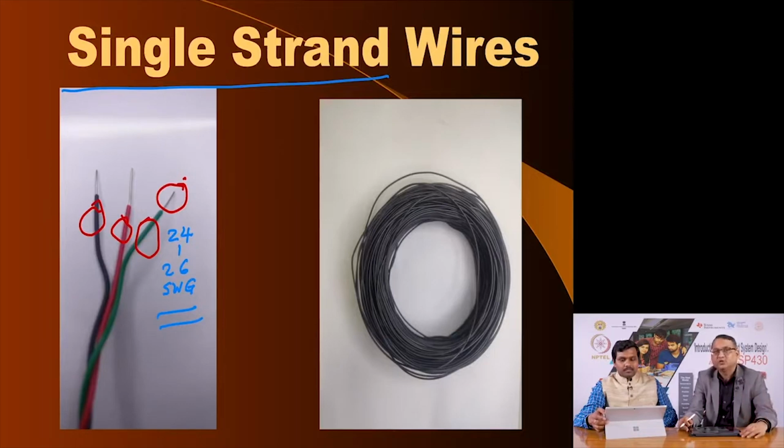On insulation, let me also make a point that the typical insulation that you would get in the market is plastic insulation. However, apart from plastic insulation, you also get such insulated wires with Teflon insulation, and it is not recommended to use Teflon insulation for breadboarding purpose, because removing a Teflon insulation is a very tough and tricky job, and you need a very specialized wire removing tool, and we do not recommend using that for breadboard purposes. Using a normal plastic insulation copper wire of 24 to 26 standard wire gauge is quite suitable.